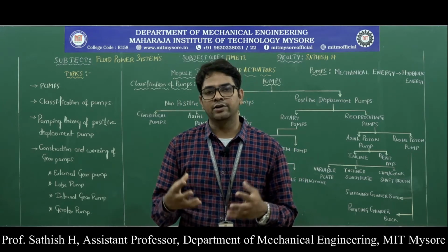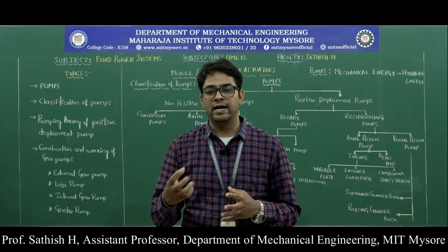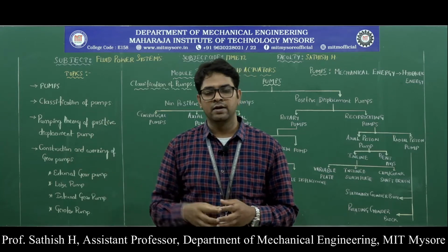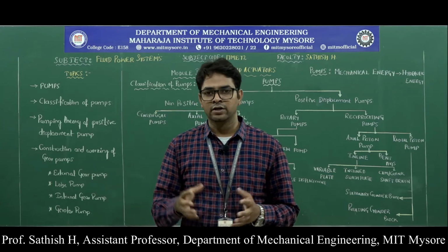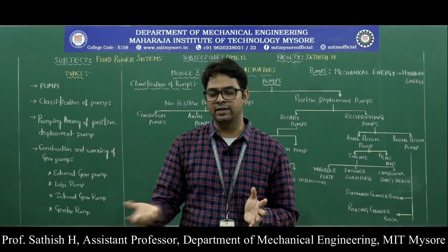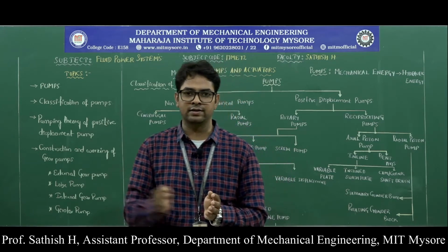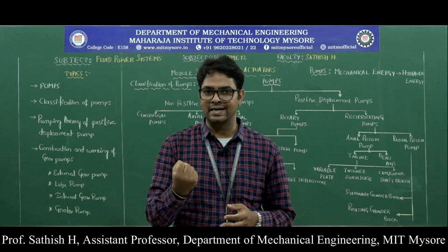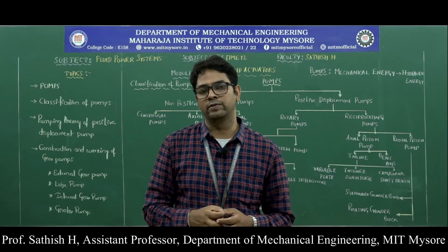In hydraulic systems, at the actuator end we have to lift the load, and when the fluid passes through the pipelines, friction is also developed. Against this friction and the load, the pump has to work. That means it should have higher hydraulic power or pressure. In the positive displacement pump we can get that higher pressure, so these are useful for fluid power systems.